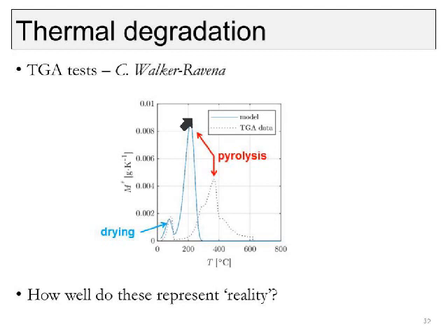So we have some questions here about whether we need to modify what we put into the model, but we also have to be careful how well these TGA tests represent what's actually happening. We've ground up the fuel in order to run them so it looks different than the natural fuel, and we have much slower heating rates than we would in a wildfire. So there's some caution we have to apply here, and it's early days in the investigation, but this is another interesting aspect in terms of being able to model everything correctly.